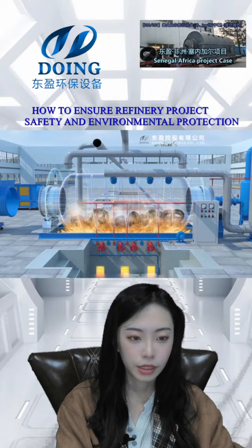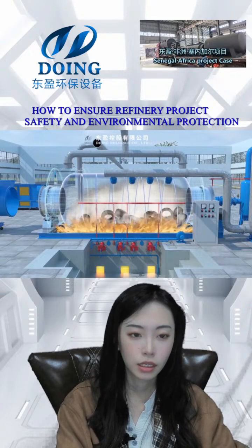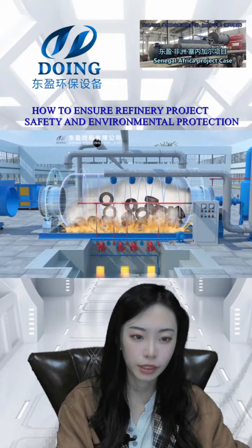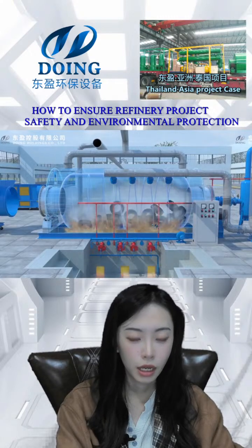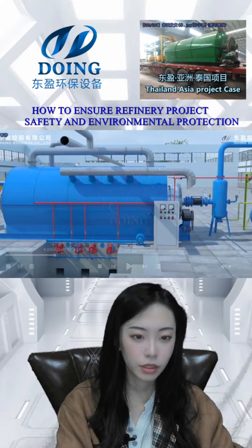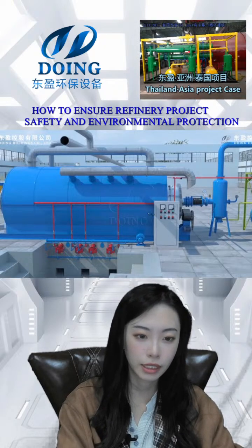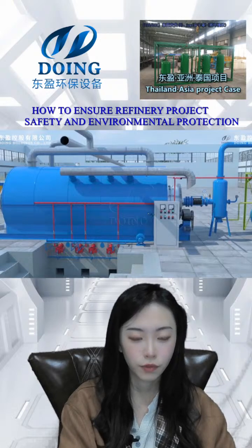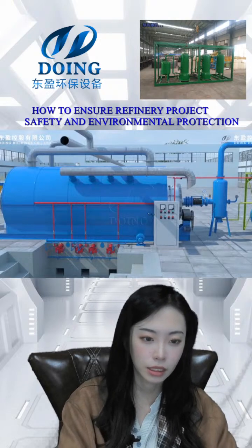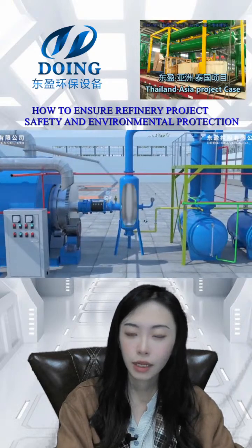And then this is the combustion system. Our combustion system is equipped with 300,000 calorie burners, and there is a tail gas burner next to each burner. After heating for about 2 hours, the temperature gradually rises, and the oil gas will be generated at 120 to 160 degrees. Then the white gas, a mixture of this oil gas and the tail gas, will come out to this outlet.